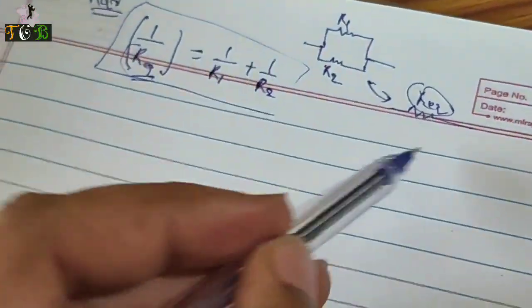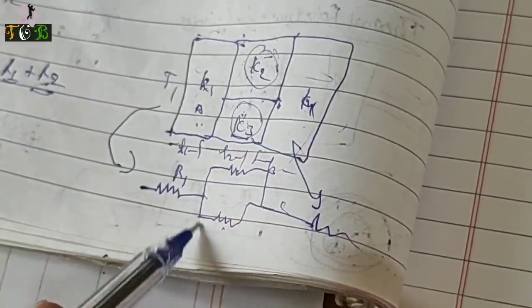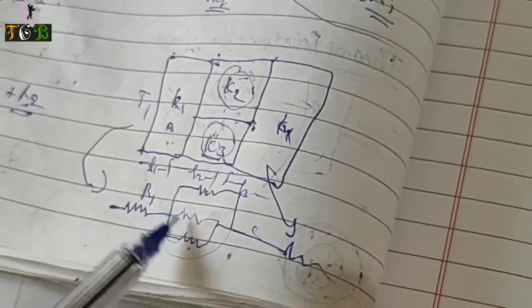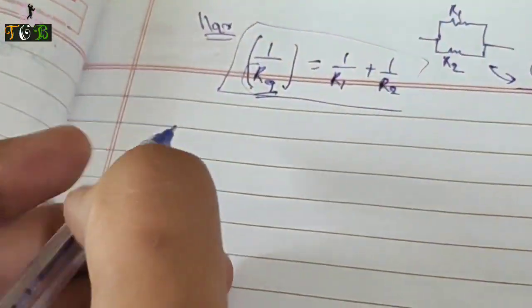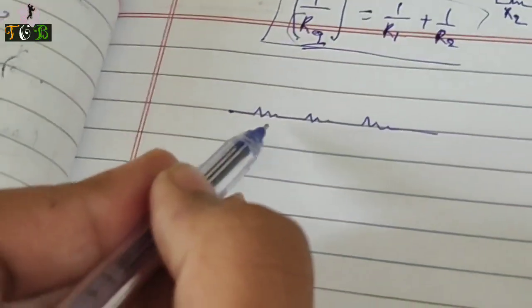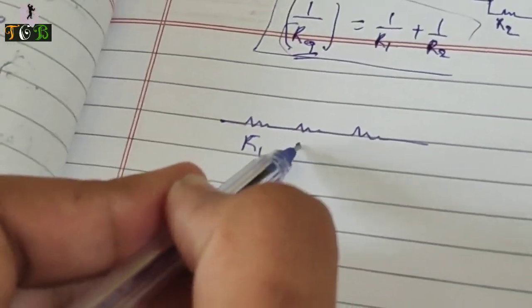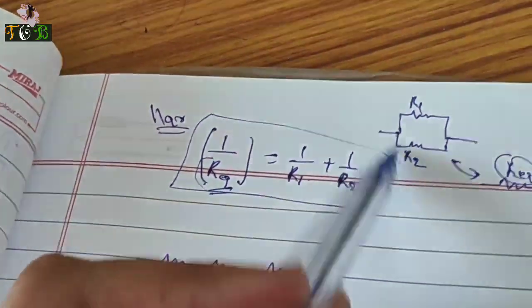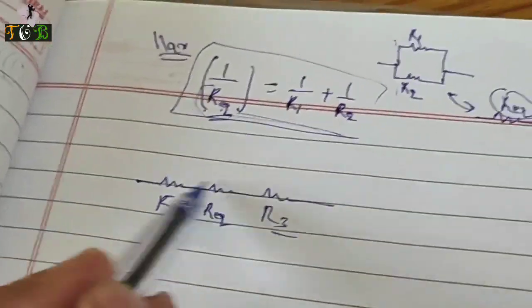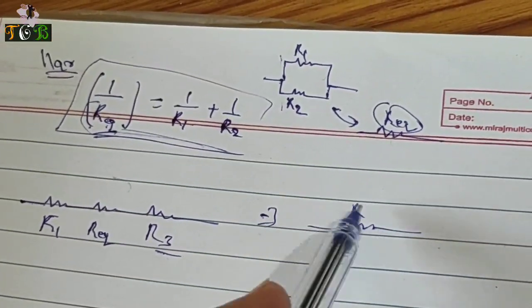So in this formula, first you have to convert this into something like this, using the parallel formula, and when you use this, your equation will become something like this. This is our first wall resistance R1, then your R equivalent from the parallel rule you will get from this formula, and R3, and now you have to add all the resistances and you will get the final R dash.